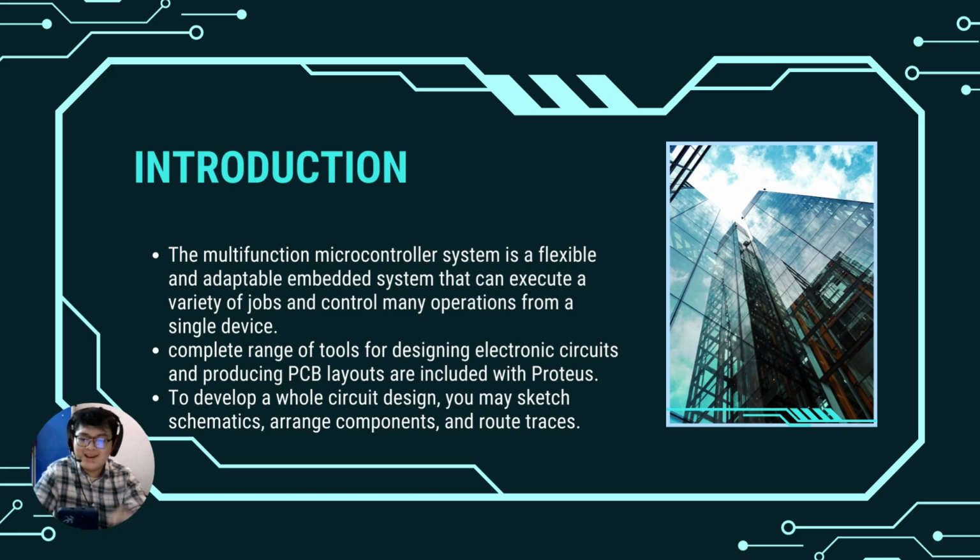As we know, Proteus is a well-liked piece of software for modeling and creating electrical circuits. We can create, test, and debug circuits with a variety of choices for electronic systems in Proteus. Proteus has a complete range of tools for designing electronic circuits and producing PCB layouts. To develop a whole design, you may design a schematic, arrange the components, and route the traces. Additionally, Proteus has tools for 3D PCB visualization, testing for design rule violations, and producing manufacturing-ready Gerber files.